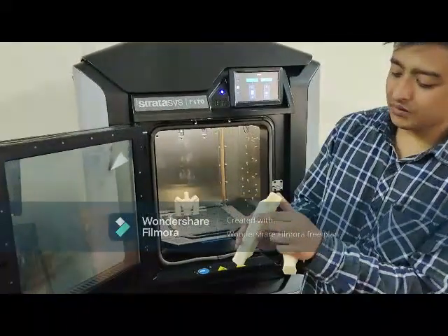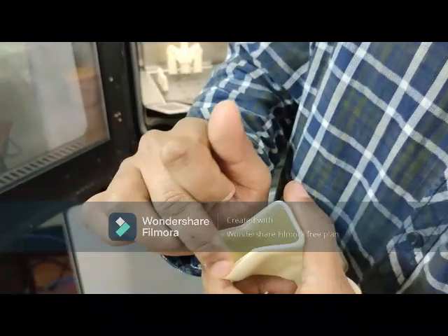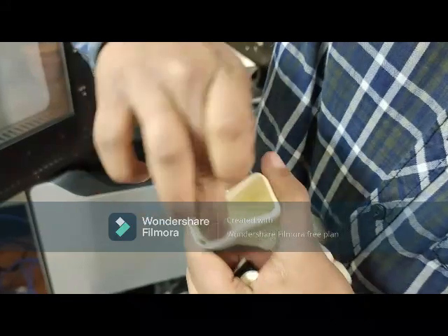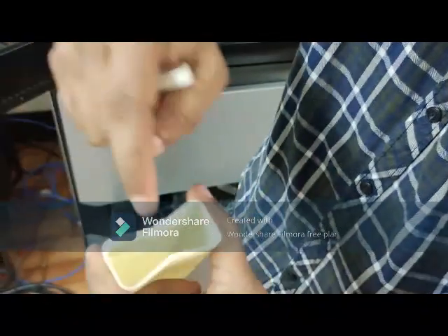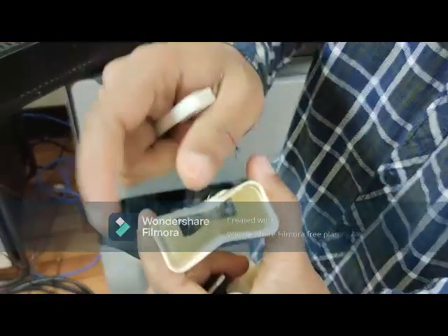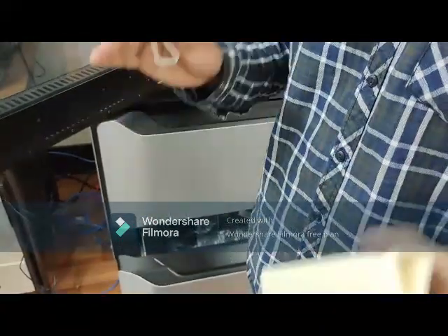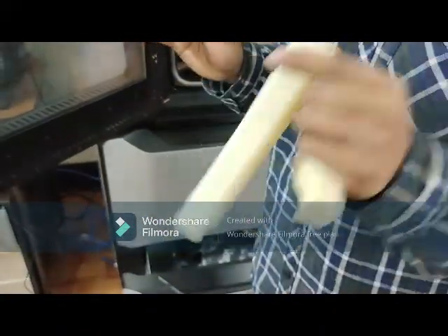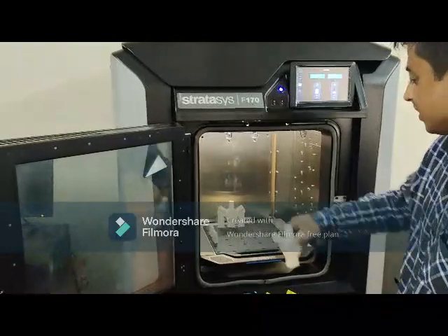So similarly, you can see here, in the purge tower also we have two different layers. Fine. This is the internal layer we have. One internal layer, one external layer. So these two layers are given, one for ASA material and one for support material. So it is continuously checking for support as well as for printing part, the main material, the model material. Fine. So we generally throw it out. So this is the part we have here.